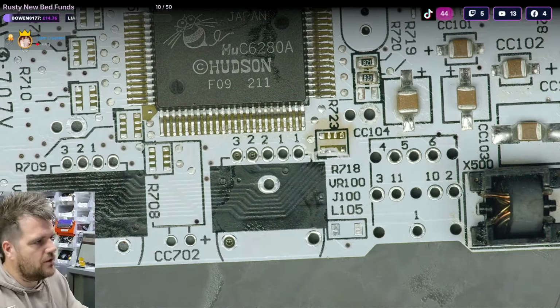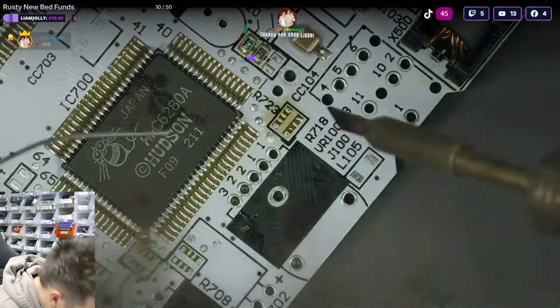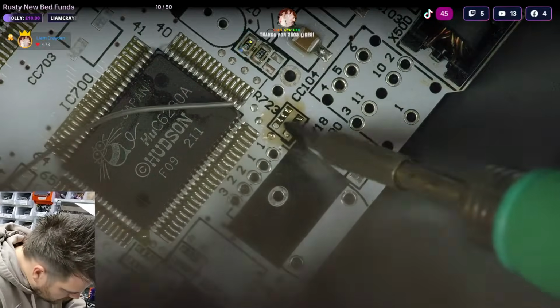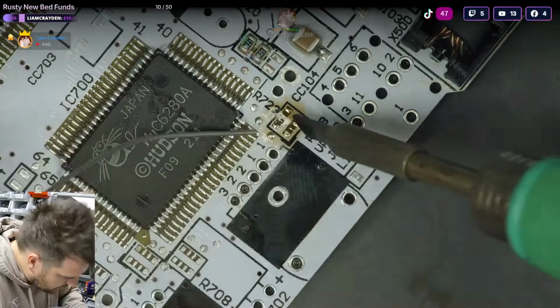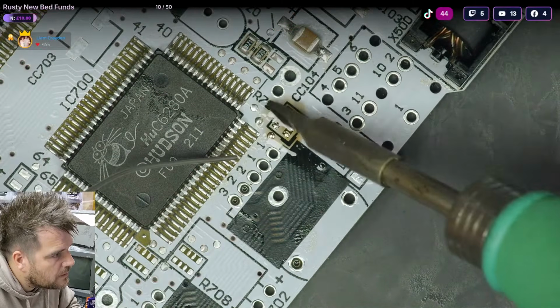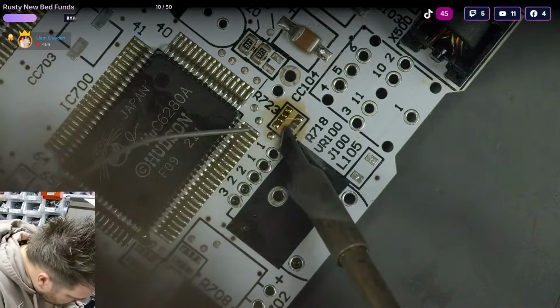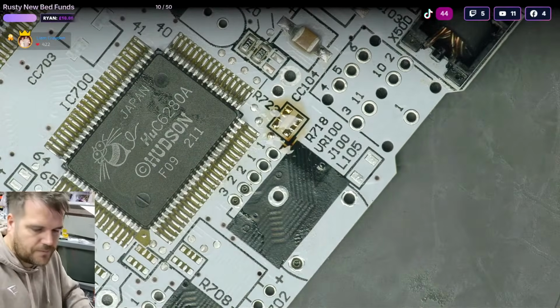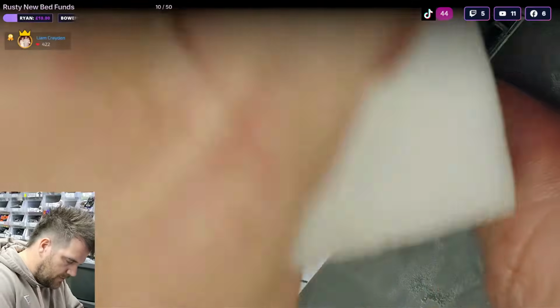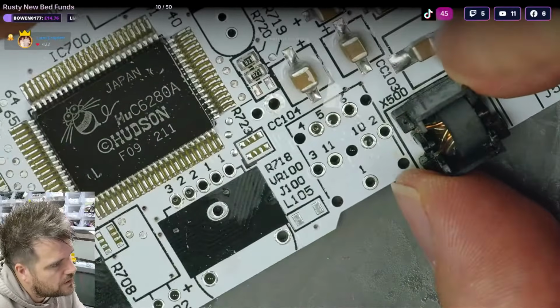So these pads here are basically 4 resistors in a row. They're usually 10k on quite a lot of them. And they're common to fail and stop the game loading. So if we pre-tin them pads, and is this iron working yet? We ideally want these to go over, otherwise hand soldering 4 individual resistors is a pain.